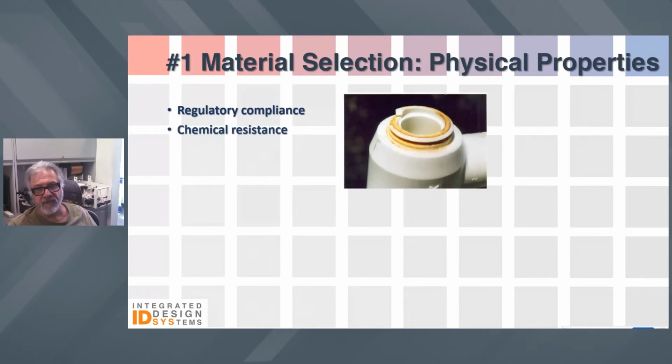Then there's chemical resistance. Some plastics have poor resistance to alkalis or chlorine or solvents. So understanding the use, as mentioned earlier, and the chemical resistance of the polymer to the chemicals that will be exposed to it is extremely important. And often this information is not very clearly defined by resin manufacturers. So it may require some testing to verify the performance of the resin.